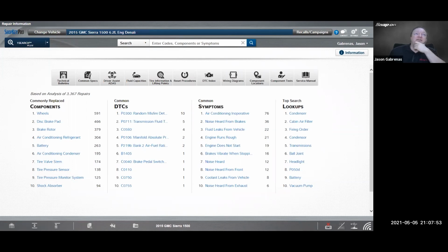Let's see, breakout at DLC, best or easiest way to scope a CAN signal? Absolutely, Bill. As long as the problem can be addressed that way. Sometimes some of the networks where we have a problem is only internal in the vehicle too, so we wouldn't be able to access it there. But most likely, especially if it's a communication problem with the scan tool, that would be the best place to go.